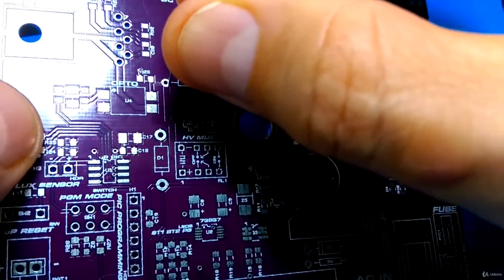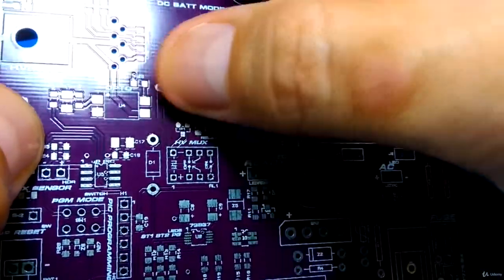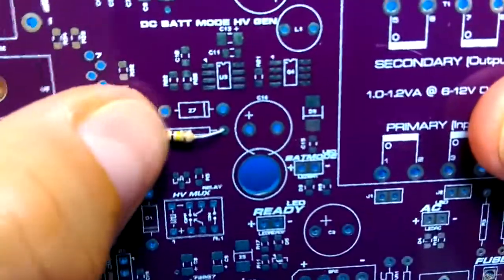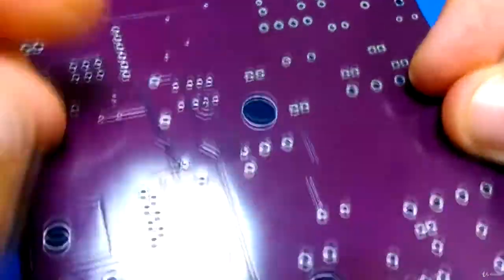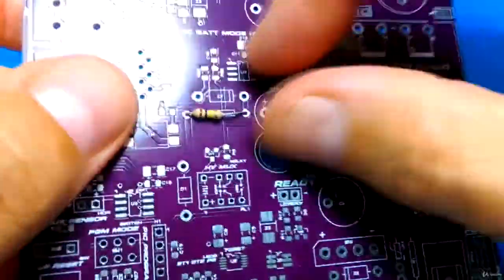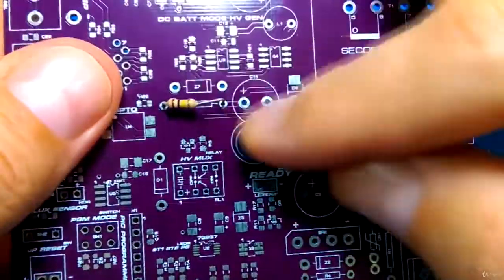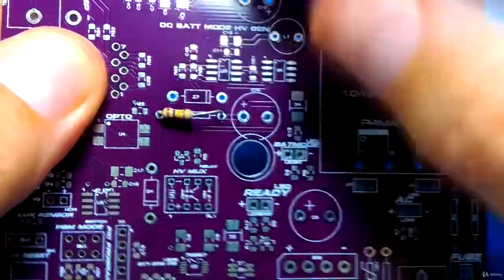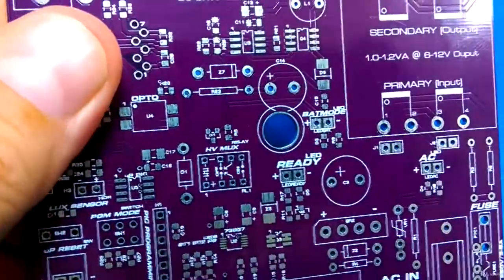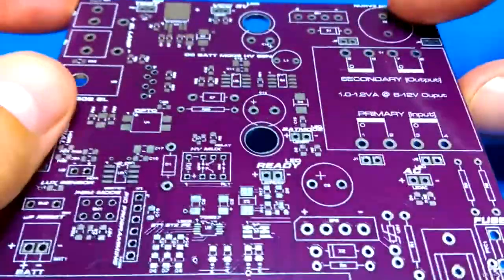So for example, if we're lucky, this will go right in here. We pop that in there, then we would turn it over and solder it on this side. So that's why it's called a through-hole component. Every one of these components has a footprint. This footprint right here is a radial footprint. And you can also see here are some surface mount components. In a minute we'll take a look at those. So that's why things are through hole. They go through the holes in the printed circuit board, and some things go on the surface mount.